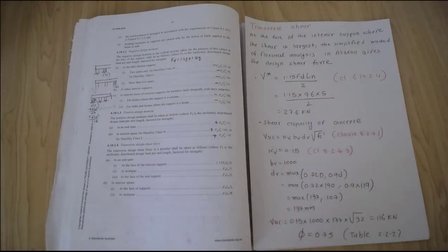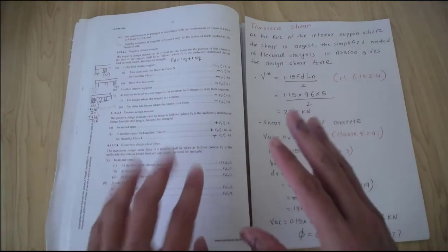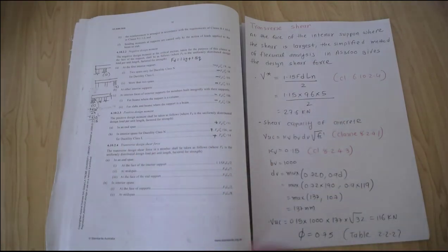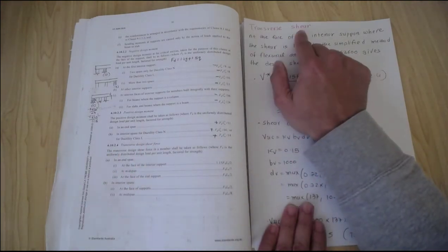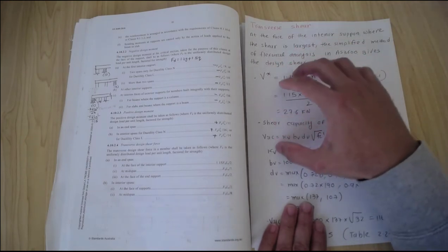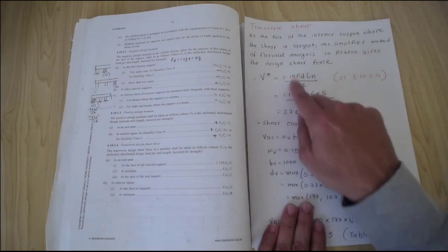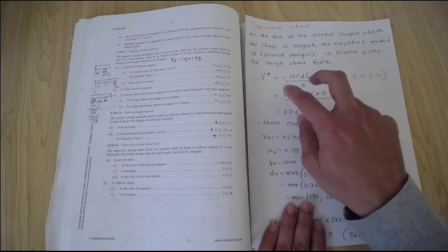We finished the calculation of reinforcement in the x direction, reinforcement in the y direction, and also the calculation for finding the depth of the slab, and we also did the deflection check. So now we are going to do one more check, which is transverse shear, whether we require the fitments or not. So first of all, we're going to calculate the design shear force.